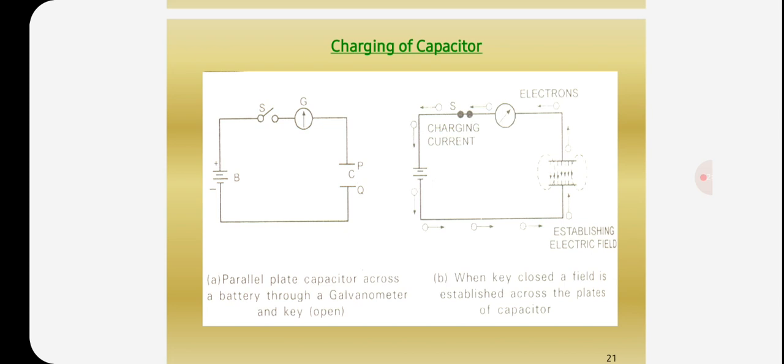This energy may be released slowly in some electrical circuits. Care must be taken when touching a capacitor because you can't tell if it is charged simply by looking at it, although it may be disconnected from the supply. It may still retain the charge and stored energy, and can give a serious electrical shock.